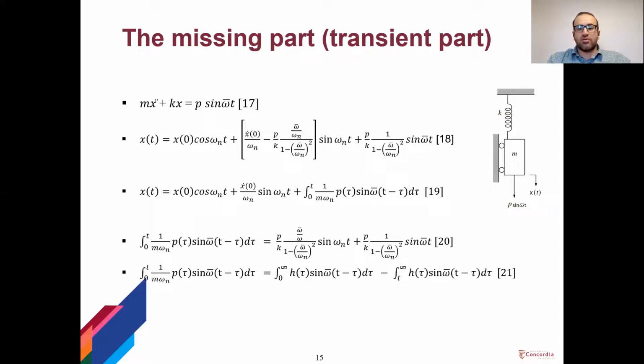So consider the undamped vibration of a single degree of freedom system under a sine load. This response can be obtained either directly by solving the differential equation that is shown in equation 18, or by using Duhamel's integral that is shown in equation 19. If we compare these equations, we see that Duhamel's integral has 2 terms. One is in the frequency of the load, the other follows the frequency of the structure.